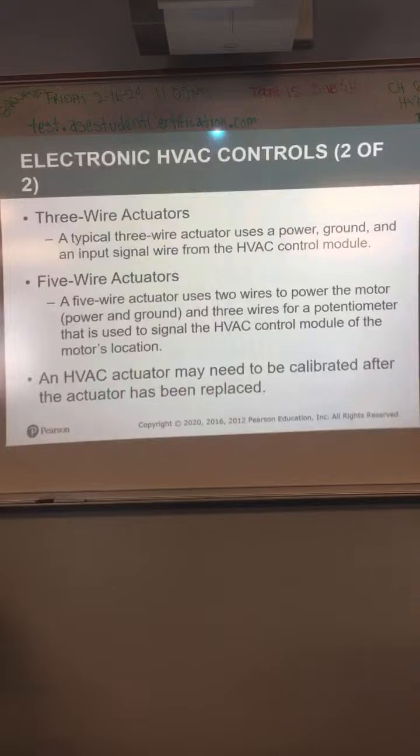So, let me give you an example. You turn your air conditioner on, you turn it all the way to cold, you turn that fan on high, and that actuator is supposed to move that blend door all the way to the cold position so you get nothing but cold air. Okay. Just because you put it there doesn't mean it goes there.